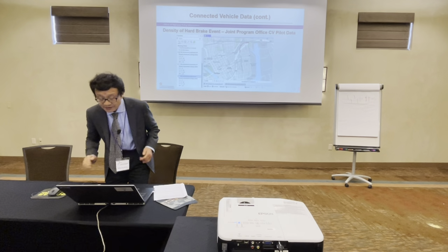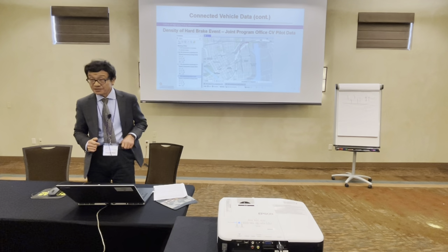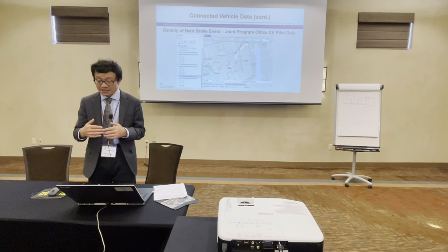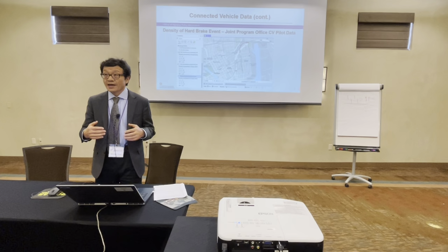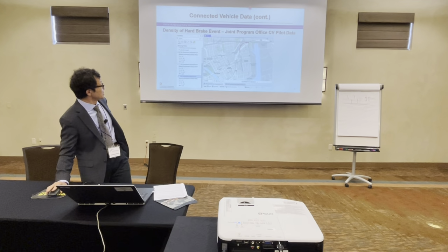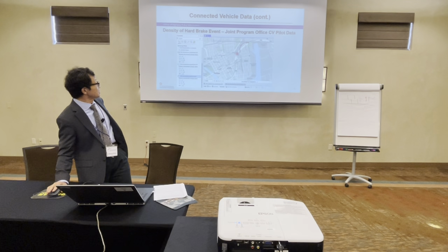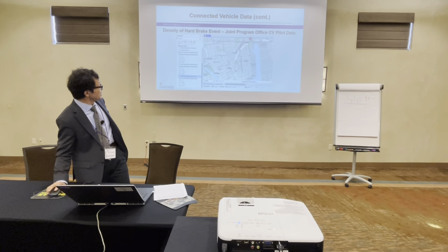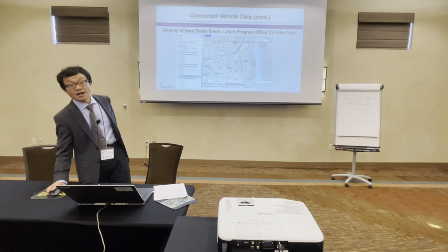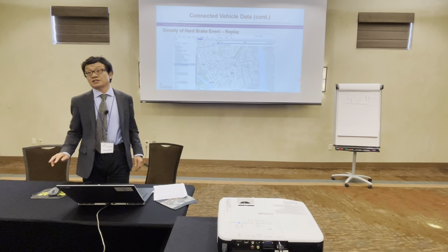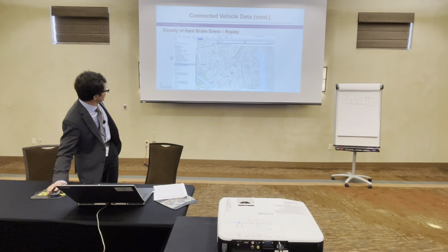By conflating those event dots with some existing GIS features, for example, the NPMRDS TMC segment, we can easily aggregate those events together with the roadway segment geometry as shown here. Like this one, it shows the density of hard brake events at this particular road segment. Also, this map is shown in ArcGIS Pro, and you can play it. Let me try.